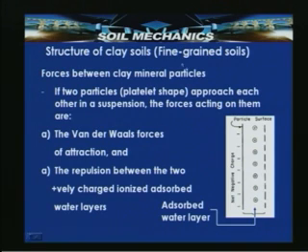If you see here, the clay particle surface is represented with a net negative charge, and a rigid layer, that is, a systematized arrangement of the ions very close to the particle. We said that is an adsorbed water layer, which imposes repulsion when another particle comes in contact, between the two positively charged ionized adsorbed water layers. In addition to this, the particles also have van der Waals forces of attraction. So, these two influence how the particles settle in suspensions.